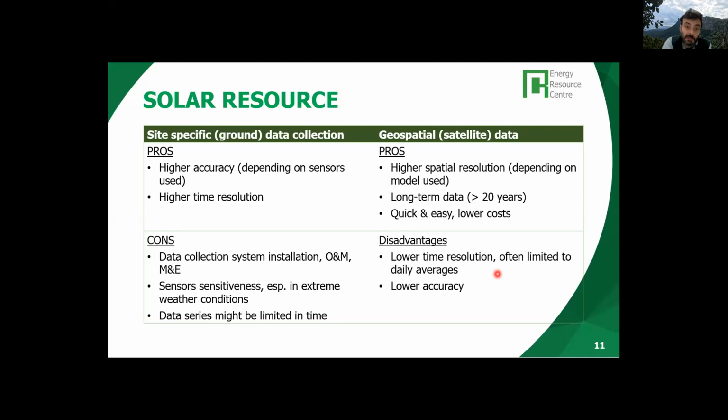But yes, we have the possibility to check long-term data, which is also convenient, because in a year we could have some particularities, or at least on very specific sites, even though the solar resource tends to be quite more stable than the hydro resource, for instance, or the biomass. Yeah, even though there are some trends depending on the cases. If you look at long time series of data, you can see differences in solar radiation of about 5–10% depending on the sites. Yeah, this could happen, so it's always good to check that point.